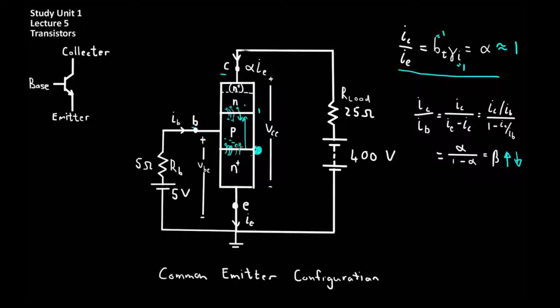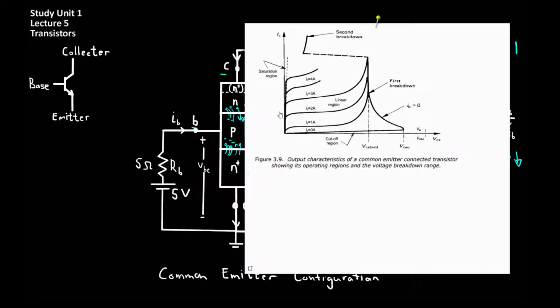If the temperatures in the silicon are managed, then this form of breakdown need not be catastrophic and the device will recover once the current is reduced. Second breakdown starts happening when there is non-uniform current density in the silicon, and this can be caused by crystal faults or doping fluctuations. In this case, hot spots start forming in the silicon and the silicon can actually melt, and when the silicon melts it causes irreparable damage to the device.